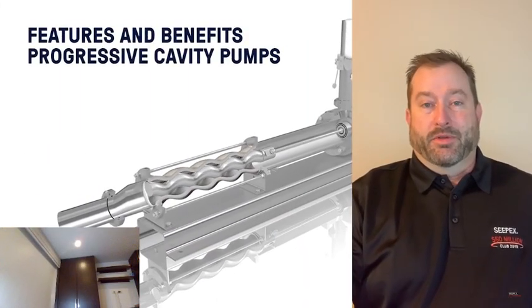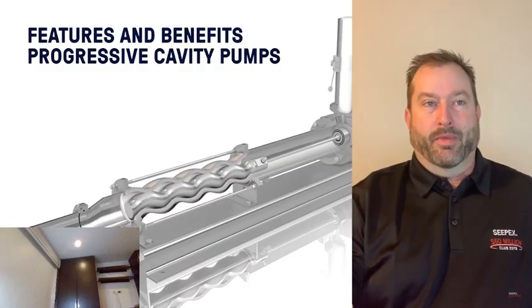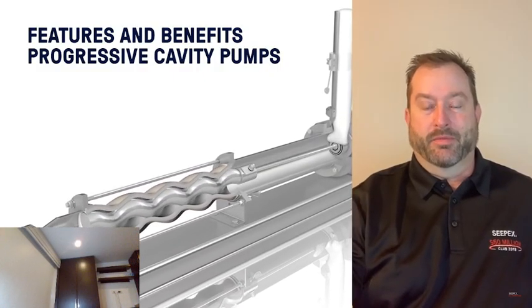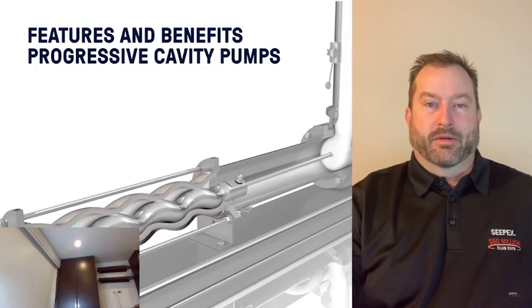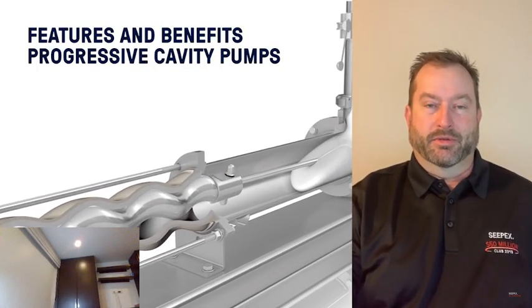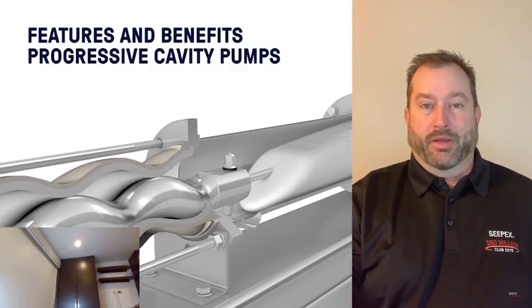What are the benefits of using a progressive cavity pump? Why would you use it instead of other technologies? One of the main concepts is the compression or the interference fit between the rotor and stator. This limits the slip, or the product going from discharge, the high pressure side, back to suction. So it's a very efficient design. It actually is very repeatable and accurate.